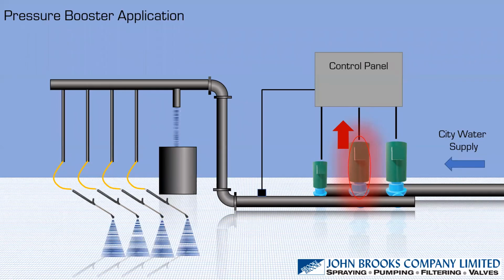Especially if it's a positive displacement pump, you don't want to be pushing all that much water right through it without the pump running. So yeah, a bypass valve, probably an automated bypass valve, would be a good alternative. Yeah, I would say, obviously every case is different, Chris, but we would take a look at that and make sure that we probably wouldn't want to be pushing liquid through a pump that's not operating.